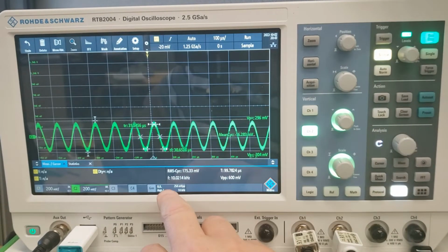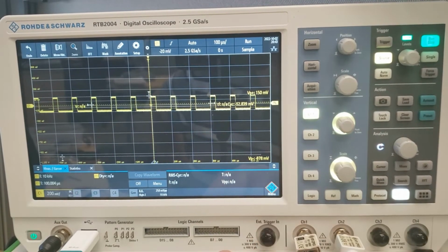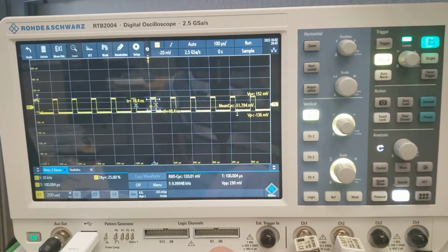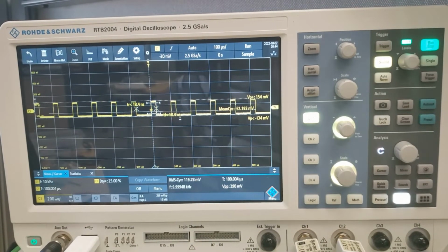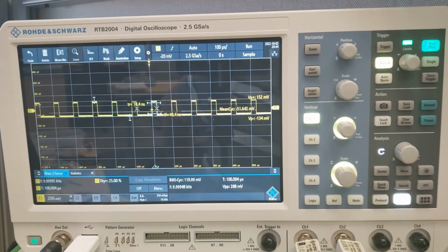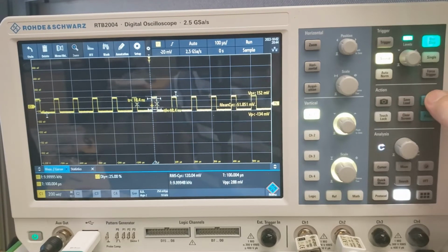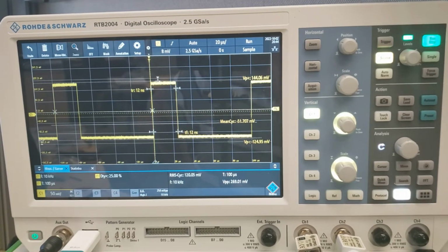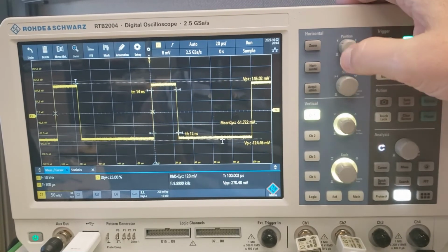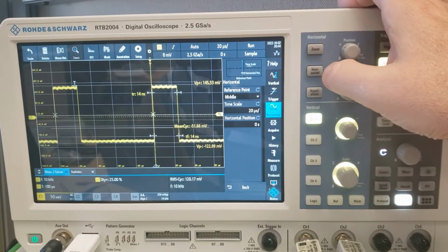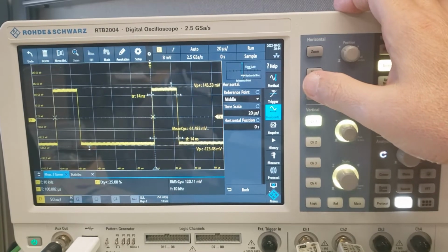let's say it's telling me the frequency is 10 kilohertz, VP peak to peak. I go up to this channel, and it's telling me that the frequency is 10 kilohertz. So I'm not sure if you have to do a separate channel at a time. As I said, I'm just new to this. Anything else? You can do auto set, the old way of if you can't figure out your signal, you can do that. I guess these are the horizontal settings. You can press that button. So there are a whole bunch of ways to get that.